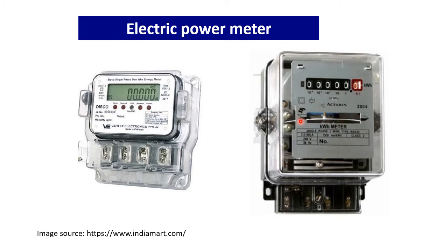Whenever current is passing, means whenever you are using the current, due to that current, eddy current will develop on this drum. Due to that it will get rotation. So due to the number of rotations here, it will show the reading. So 10 rotations is just 0.1 unit, and at 1000, it will be 1 unit. Like that is the calibration. Simply, whenever you are using the current, eddy current will develop, and due to that it will rotate. With respect to that, we are measuring the reading, that is the energy meter phenomenon.